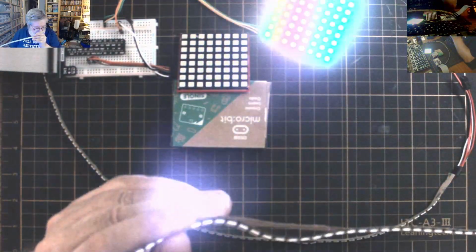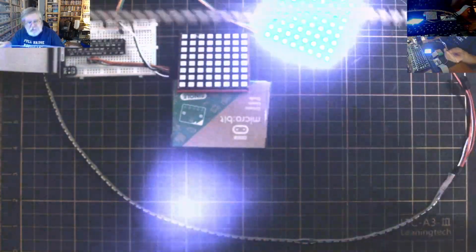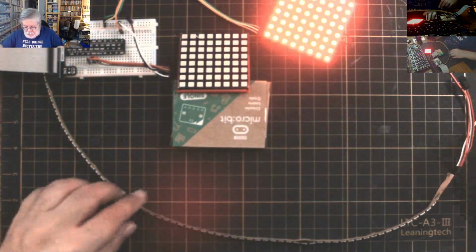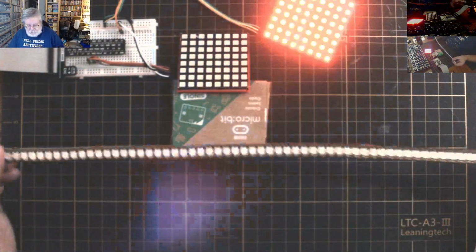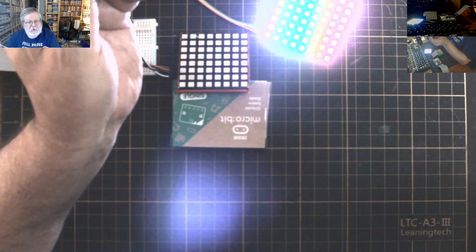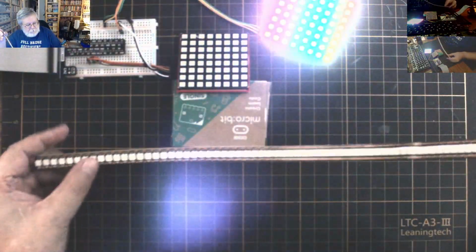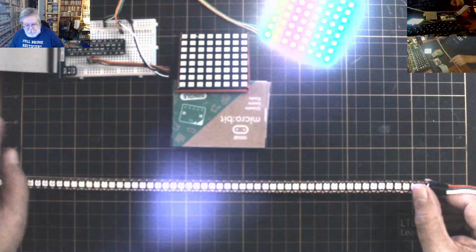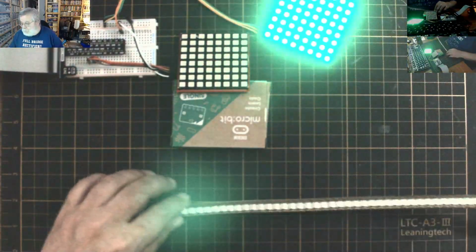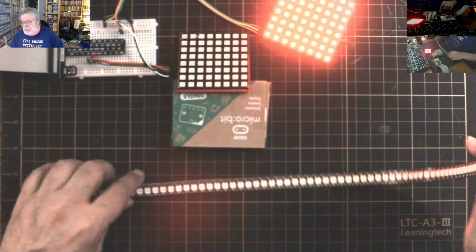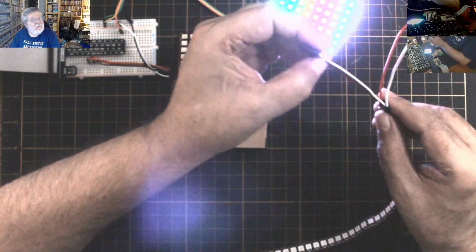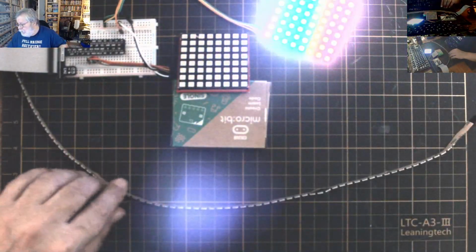This is 72 pixels. Actually I was using this one, 72 pixels. But I did find that this one has a shoddy connection somewhere in here. Now, I'm not 100% sure it's a shoddy connection, because this is the type of strip where you have to be very careful with the Raspberry Pi, because I cannot direct drive this strip with the Pi's 3.3 volts. That's where that level shifter comes in. The green wire on here, which I believe is the data line, has to be driven with a level shifter.